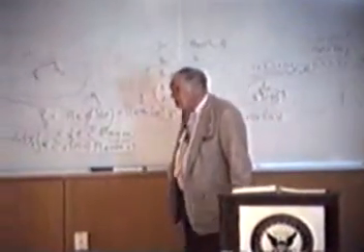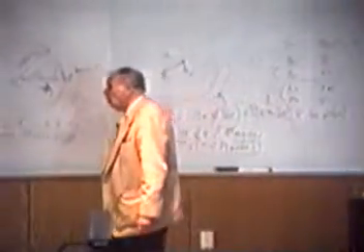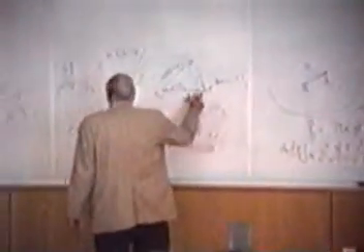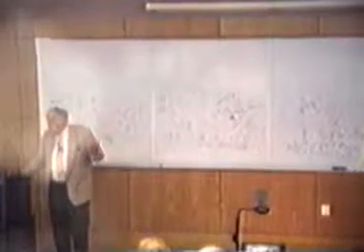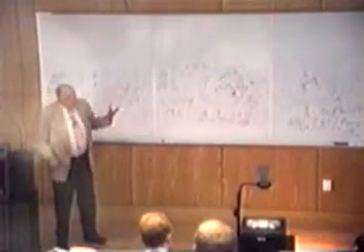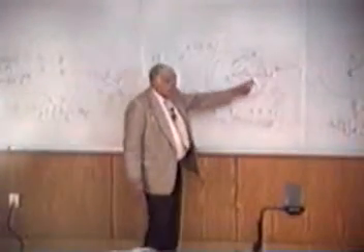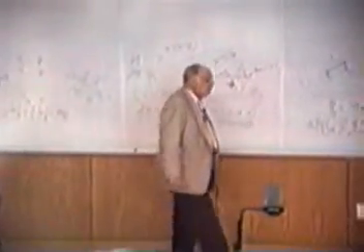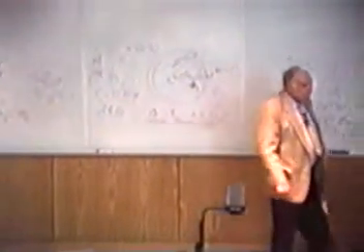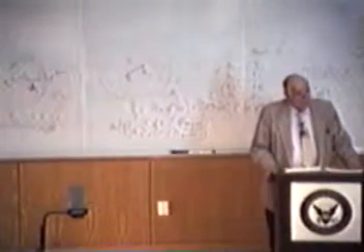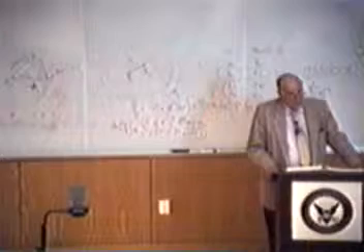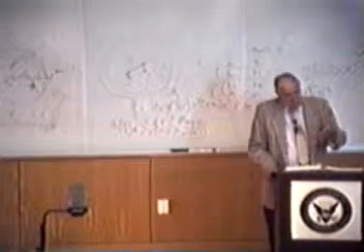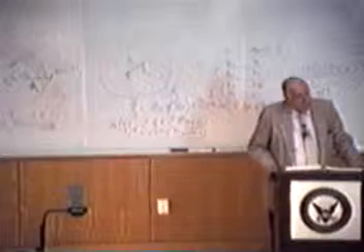On the other hand, Shannon does tell you, if you want to be efficient, you have got to have a large code because I've got to have that thing apply. If I build a system which will correct 10 errors and almost all the time is only correcting 5, I'm wasting capacity, right? I must be very close to correcting the maximum number I can. And that's why you find in communicating from the satellites back to Earth, you have maybe 5 watts or less. If there's solar cells way out there, the sun isn't very bright, and if it's a nuclear energy power source, it's been running for some years and it's got too weak.